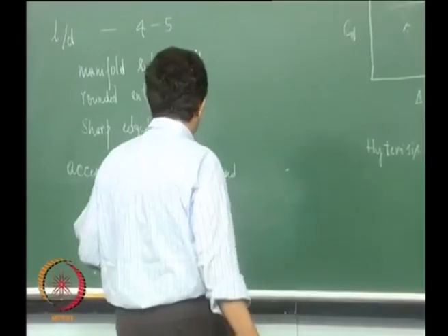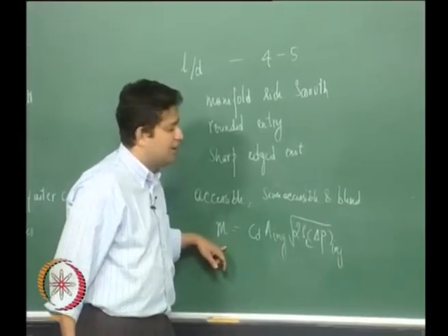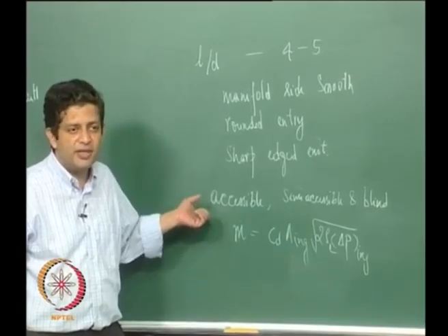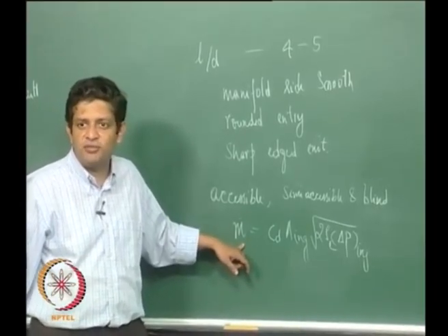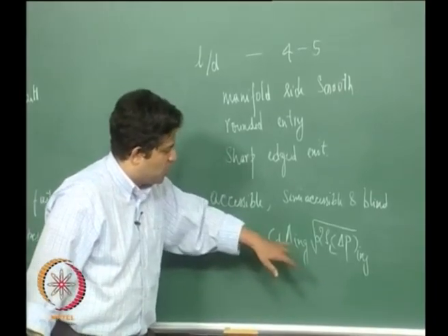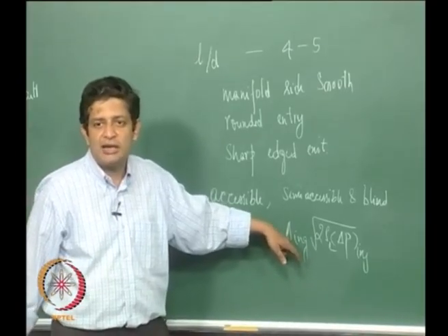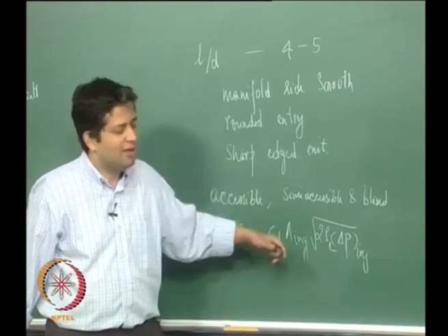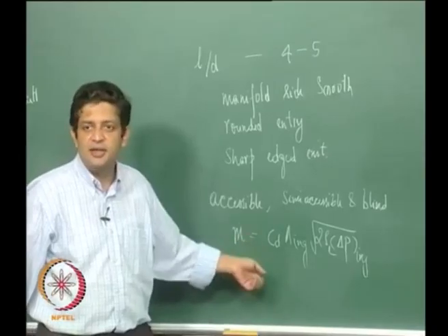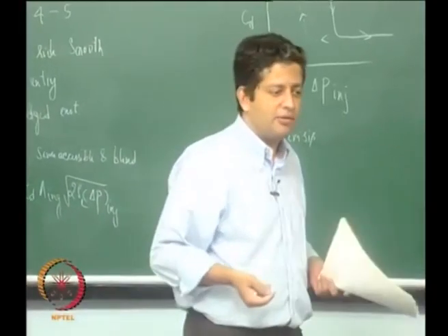So we have now learnt the mass flow rate through an injector, and if you remember, we can calculate the mass flow rate of fuel based on the thrust and Isp, right? Now the other information that we need is the area of injector that we need to use in order to design a particular liquid rocket motor. If we know this area or the diameter, then we can design these injectors. Now how do we go about designing this injector size?